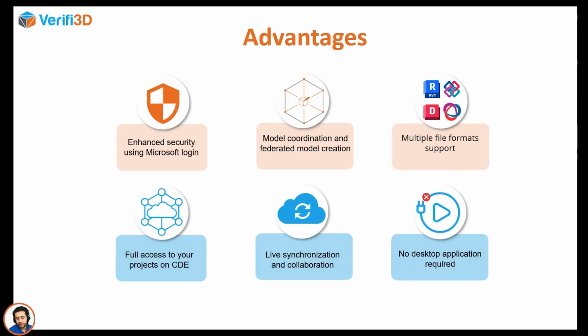Now, the advantages for using Verified: you can have a single sign-on feature where you can log in using your Microsoft account. As I told you, you could create different federated models on the same platform. We support different file formats, so not only Revit or IFC, but also DWG files, BCF files. And as long as you have full access to your project on the CDE, you can also have the same access on Verified, because we have some kind of live synchronization between the two solutions. And when I say the two solutions, I mean Verified and the common data environment.